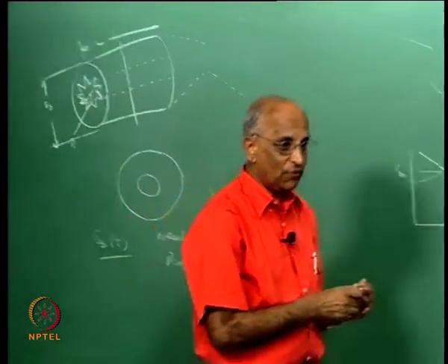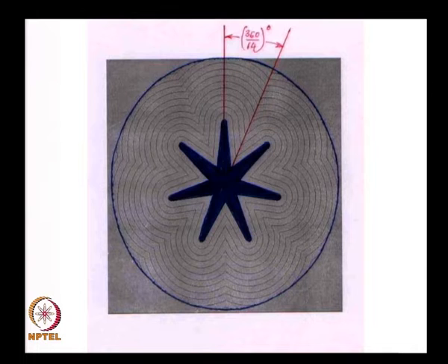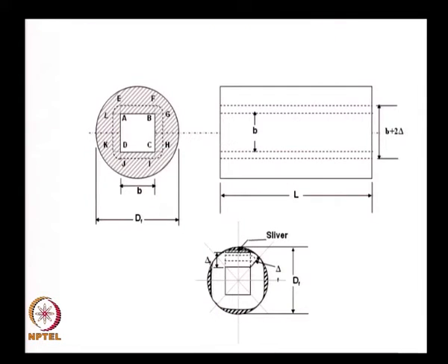At the next instant of time, the surface is again evolving, it goes over here, comes over here, I can calculate this, and this is what I wish to calculate. Similarly, maybe towards the end it comes over here, this is the shape. Initially I have these surfaces, but as it progresses it becomes something like a circle. And why does it become a circle? Because a point, when it burns, goes into a circular fashion, and therefore to be able to understand this type of burning, I first deal with a very simple case.